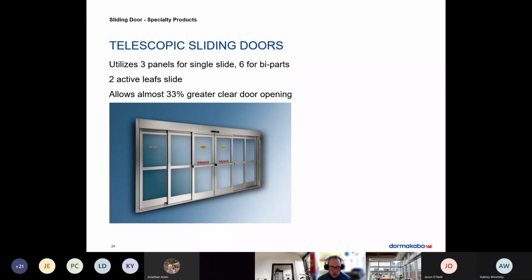The limited sightline doors, it seems like that's following more of a European approach where you're relying on the glass pane itself to provide rigidity to the frame, versus more traditional storefront, where you're relying on a stiff aluminum frame and the glass is within that. Are those appropriate for heavier use or abuse environments?